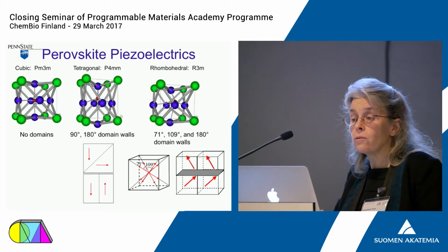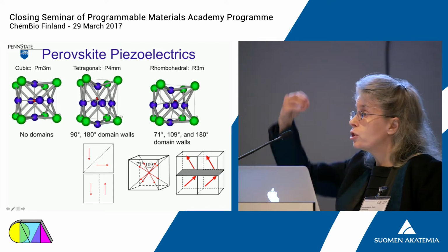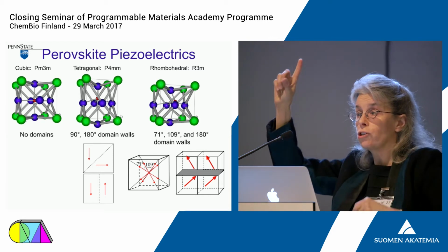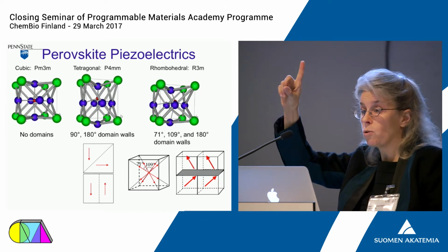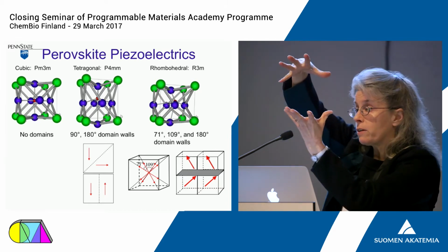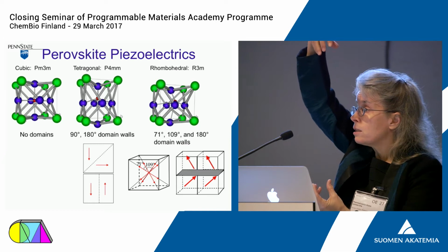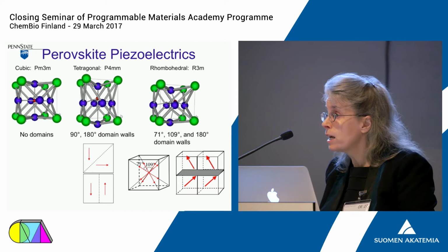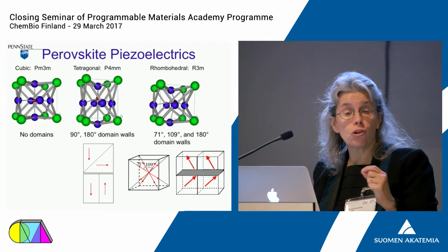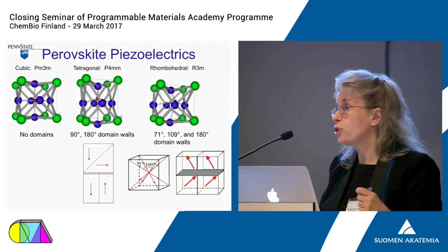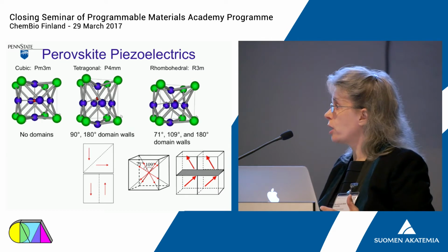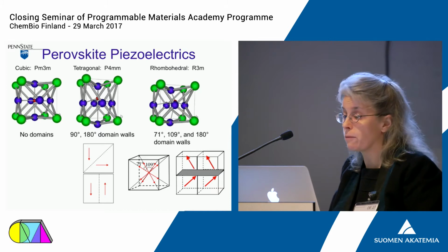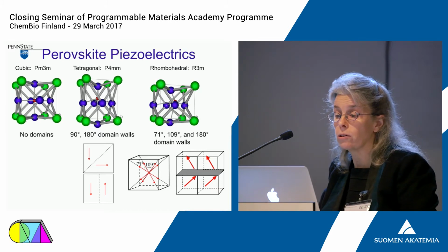And as it does so, the center of positive charge shifts up in the unit cell with respect to the center of negative charge, and we produce a spontaneous polarization. And as the material develops this polarization, it elongates parallel to the polarization and contracts laterally. And that points out that these materials have a strong coupling between polarization, which is an electrical signal, and shape, which is the mechanical signal. So fundamentally, this will be the origin of the piezoelectric coefficient in these materials.